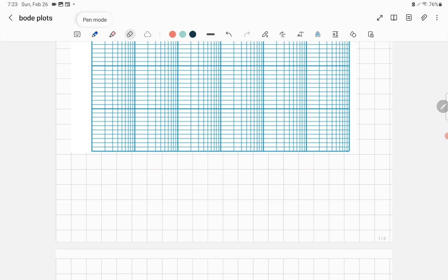For example, if you are going to start from 10 hertz, then you are going to multiply by 10 each time. I'm not talking about the small division. That's the major division, and the little division inside, that's the internal division. So that's 10 hertz. This one we multiply by 10, that would be 100 hertz.